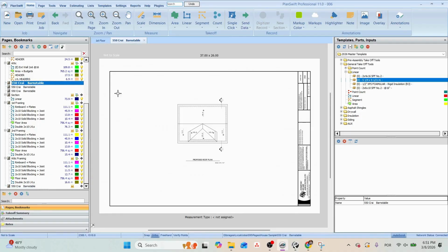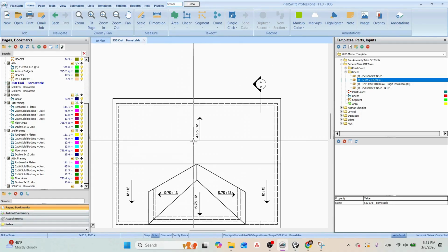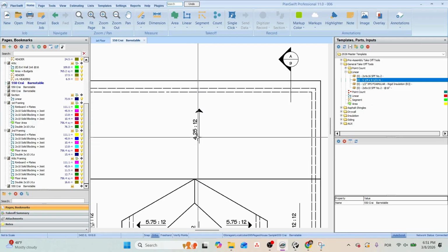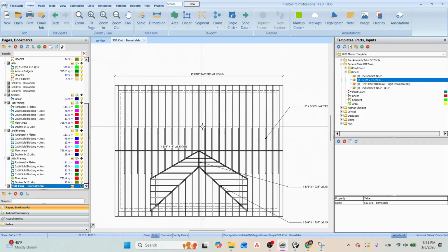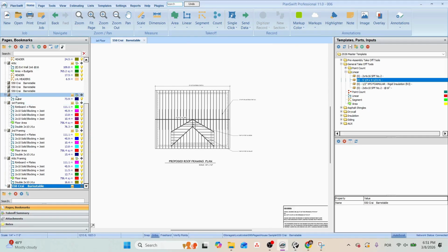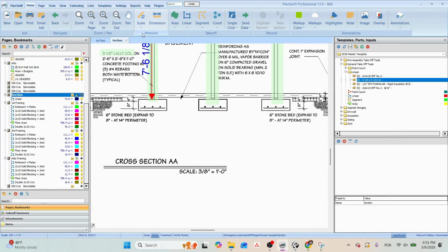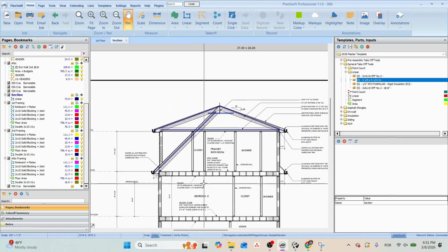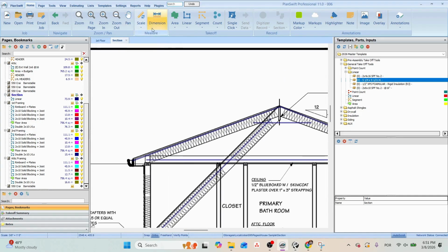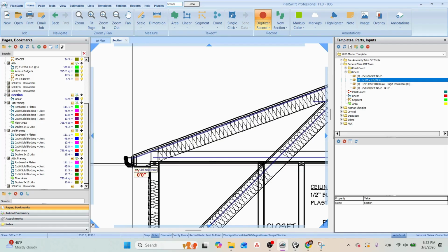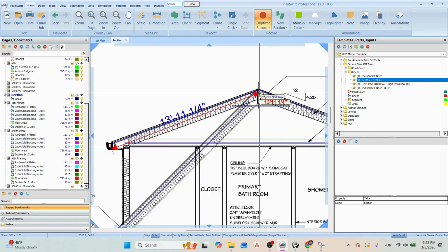Let's go by the roof. Up top, we have a pitch of 4.25 by 12. So all these joists here have a certain length, which is, let's measure scale. Let's see a rough number for these rafters. 14 footer.